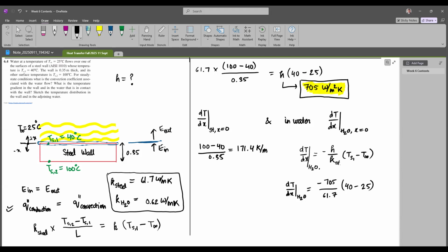So here, because it is just the temperature difference, that's why we can take degrees Celsius as well as Kelvin values. But if you're solving a radiation problem, please be very, very careful. It's usually very misleading, and people end up using degree Celsius, and usually it's raised to the power 4, and it's a big mess. So always use Kelvin to be very safe. But if you are confident, you use degree Celsius.